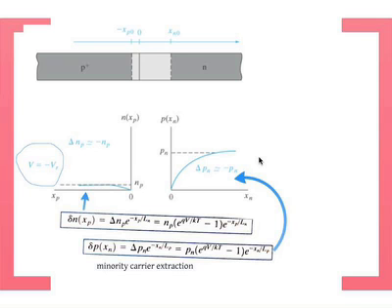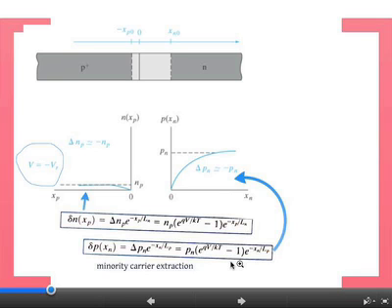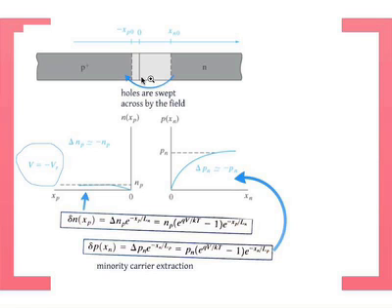And V is negative, so you have minority carrier extraction. If V is negative enough, then this number becomes minus p_n. Essentially, the picture is that the holes are swept across by the field. Like I said, when you do reverse bias, that field is increased, it gets stronger. So any hole that accidentally gets into the depletion region essentially gets swept across really fast. And if your field is large enough, you can actually tear the electrons and holes out of the covalent bonds. We'll talk about this. And they can sweep across the junction as well. And that's a very specific phenomenon for reverse bias.